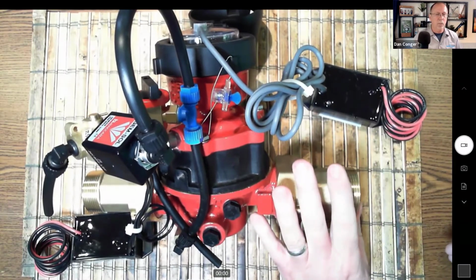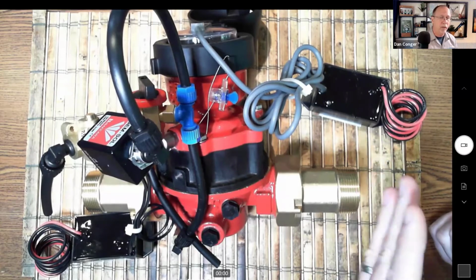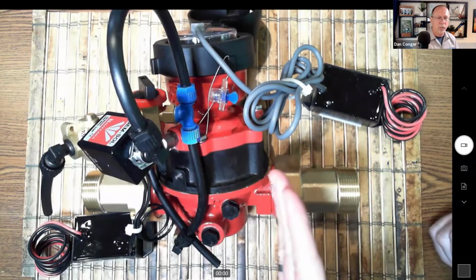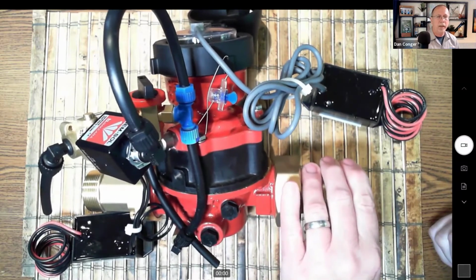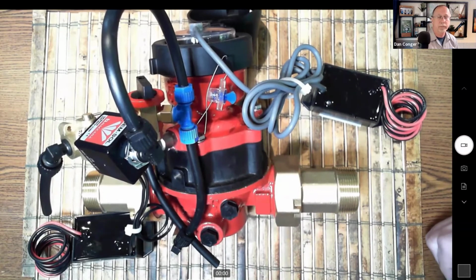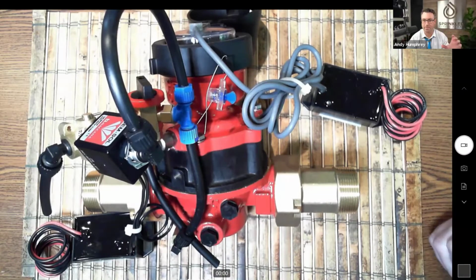So when we talk about setup in a little bit, you've got to have clear pipe diameters, depending upon the device itself, to allow that flow to stabilize before it moves through. Not necessarily the case with this, right? We can shove this into very compact areas for retrofits. Yep, because of the horizontal turbine that's in there. If you think about that paddle wheel, water can sort of scoot by, for lack of a better word, but the horizontal turbine doesn't need that stream straightening. It essentially has stream straightening in it.